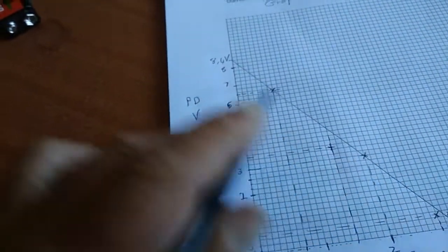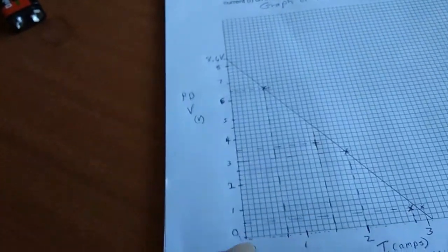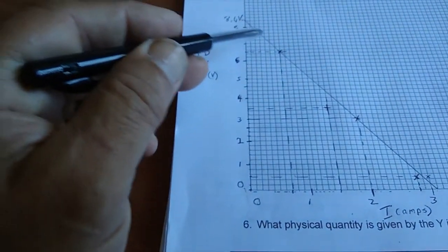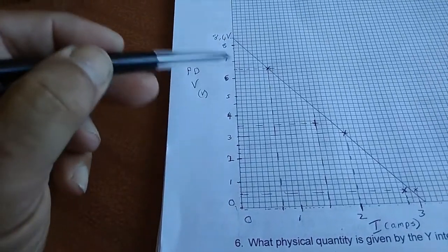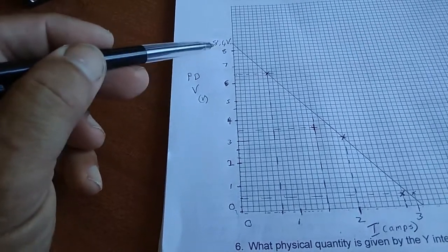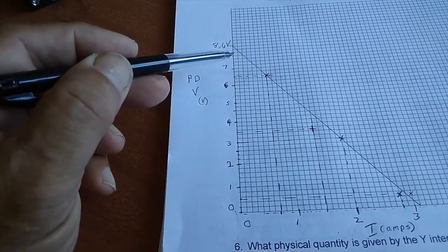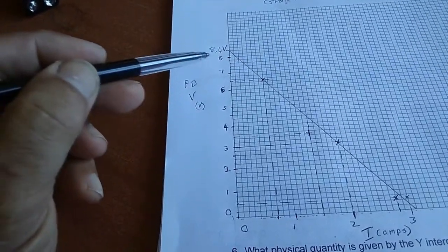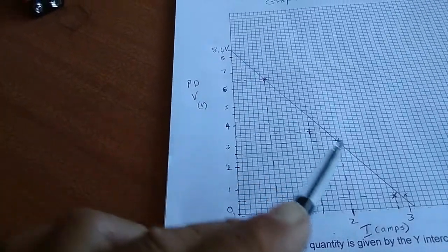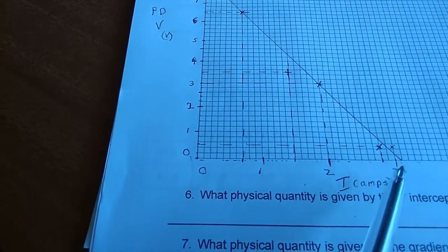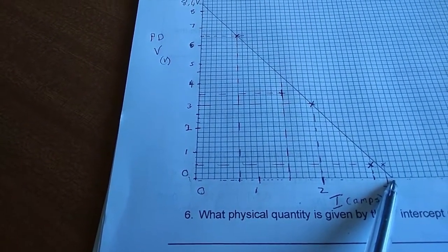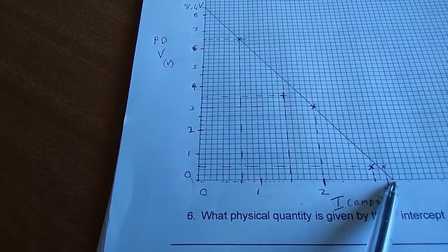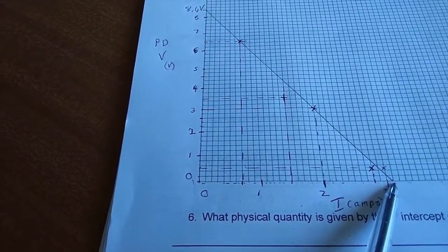Look at that relationship between volts and amps. As the current rises, the voltage falls. So we start with no current, big voltage. What do we call that voltage, the maximum voltage that we can get at any time when there's zero current? Well, you know the name for it. And then watch as it falls. It's falling in voltage as our resistance gets less. So there would be the point where there's zero resistance, maximum current that flows. Zero resistance would mean maximum current, but it also means least voltage.